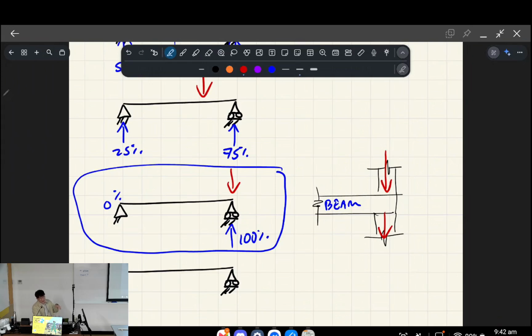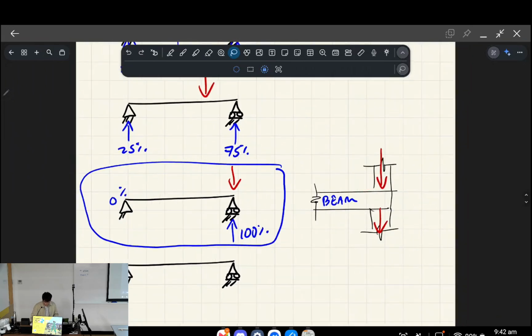So the column underneath acts as your support, and the column above acts as your point load when you're doing a free body diagram of the beam. So none of it interacts with the beam. It doesn't get more complicated when you've got offsets and stuff like that. But if this is perfectly aligned, that's how that load transfer mechanism works.